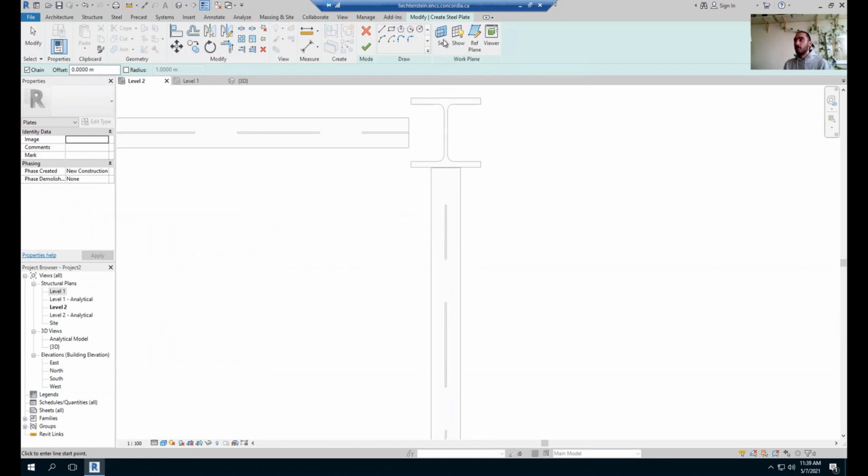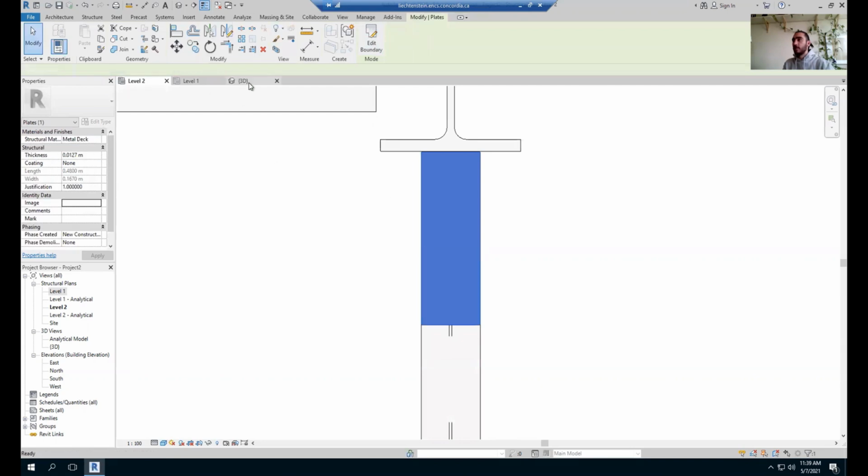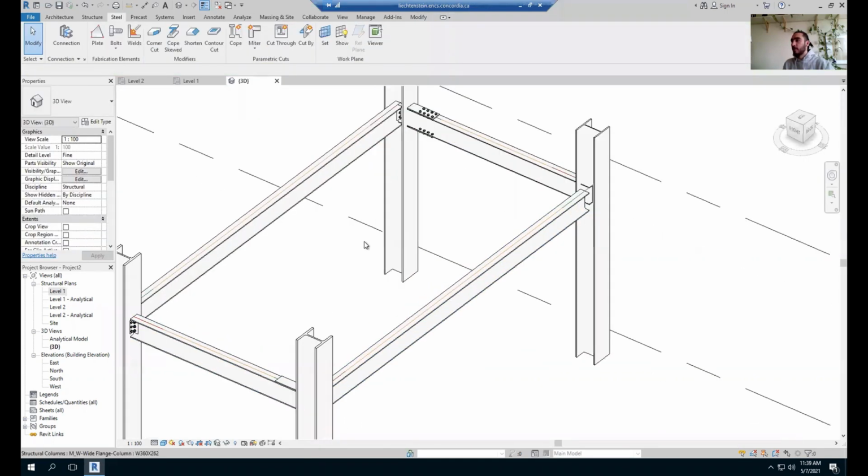Anyhow, so far we're all fine because we're working on the top flange. So I start putting on my rectangle there, right? Let me see what the sizes should be. So it should be 0.48, right? So select everything, making sure that I'm exactly having 0.48 from the other side. Click on finish, right? Going to get back to the 3D.